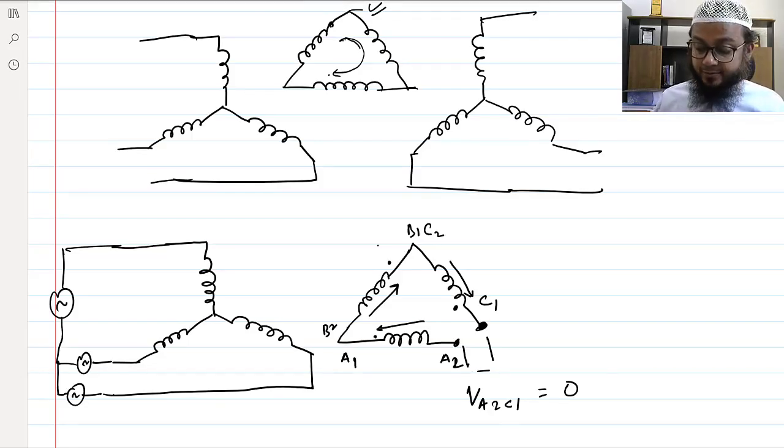But you will see that obviously the fundamental component is 0, but in this kind of condition, because the neutral is not grounded here, the voltage will have a third harmonic component in it, and the sum of it won't be 0. Then in the second part of that experiment, we grounded this terminal.